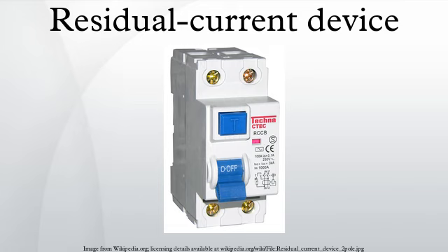To implement this arrangement, it was common to install a consumer unit incorporating an RCD in what is known as a split-load configuration, where one group of circuit breakers is supplied direct from the main switch and a second group of circuits is supplied via the RCD. This arrangement had the recognized problems that cumulative earth leakage currents from the normal operation of many items of equipment could cause spurious tripping of the RCD, and that tripping of the RCD would disconnect power from all the protected